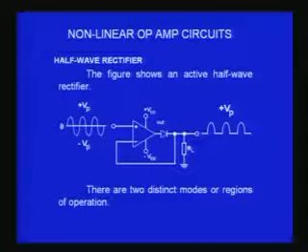In this configuration, you can see the feedback loop from the negative input is connected at this point after the diode, and the diode comes at the output of the operational amplifier. This resistor RL is the load resistance, and so this is a non-inverting buffer type of thing except for the diode. So, when I give a sine wave input here, I must get a sine wave output here if the diode is not there, but because the diode is there, something else is going to happen. Let us see what is going to happen.